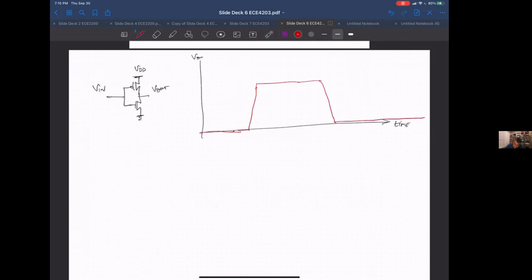And then it'll basically be a pulse on my input. So this output is driving another bunch of gates. All these gates, if you sum up all the inputs, are going to look like some capacitance hanging off of here. As we'll see, the output is inverted.